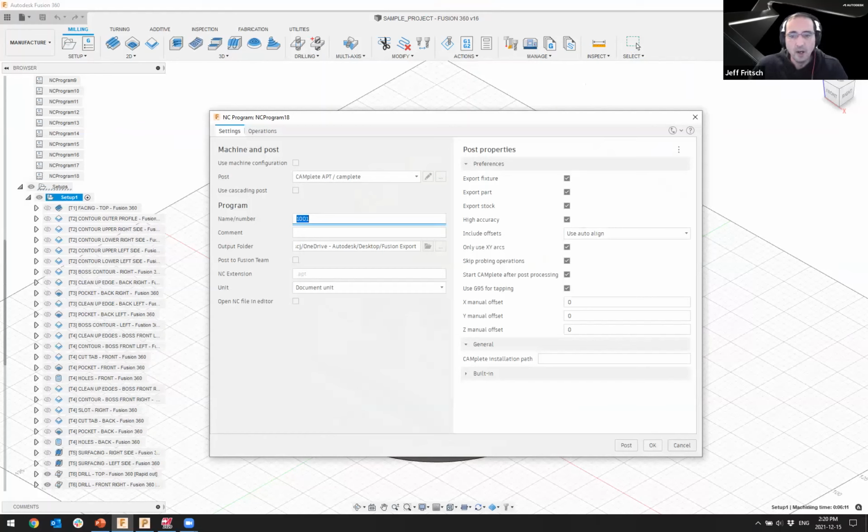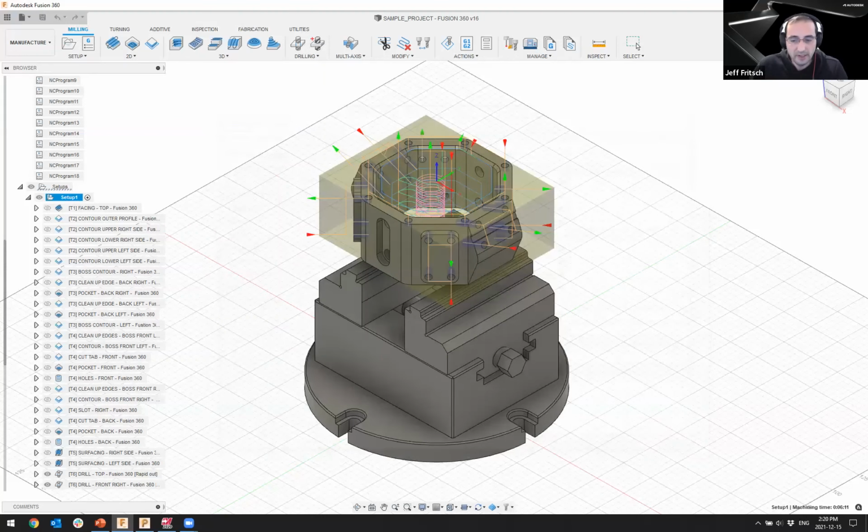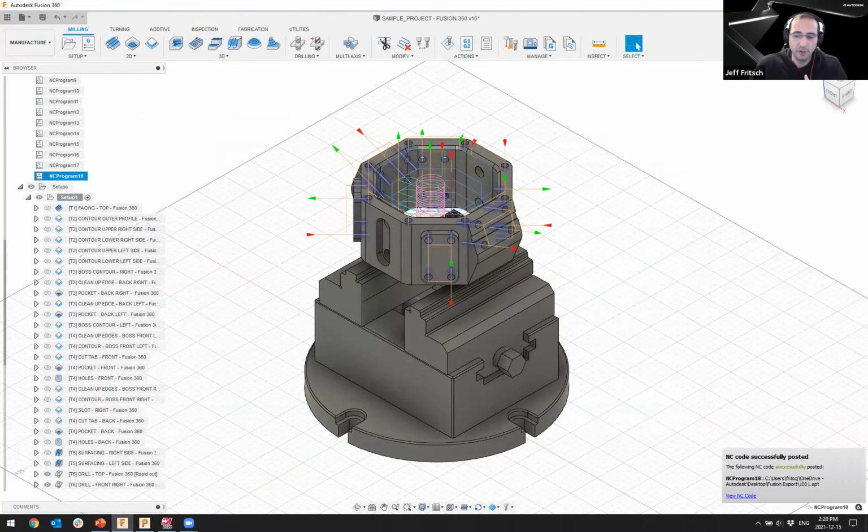the post-processing there. So that is done typically in Fusion through the CAMplete APT output that will, of course, grab all of the toolpaths, the tool information, so tool holders, all of the different models for part, fixture, stock, where everything is located, and start the software from there. So it's a very smooth export where basically you just say, yes, transfer all of this information over. I can get notified when everything happens. And then the software, Toolpath or CAMplete, will now pick it up and start loading all of those elements.